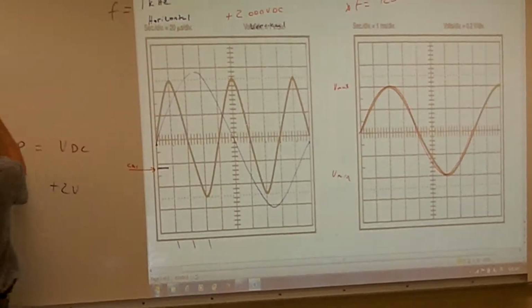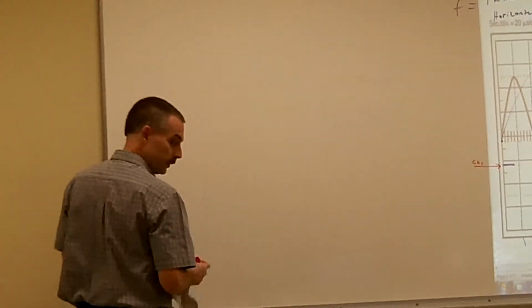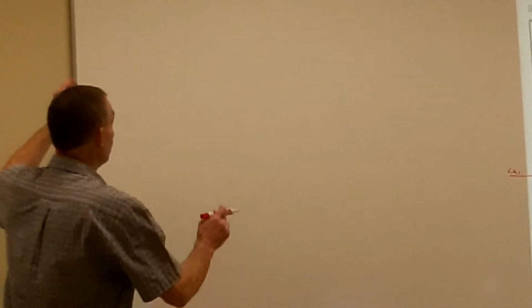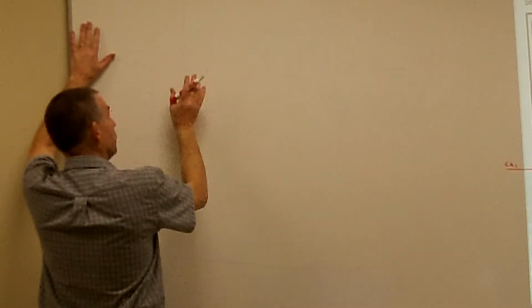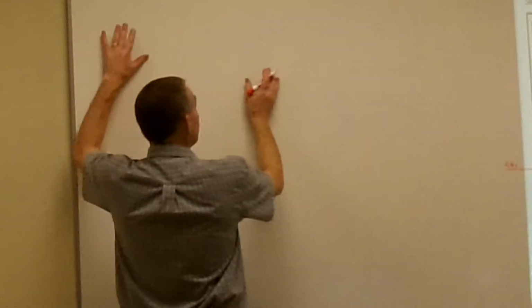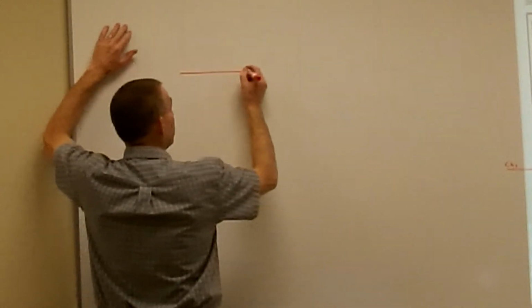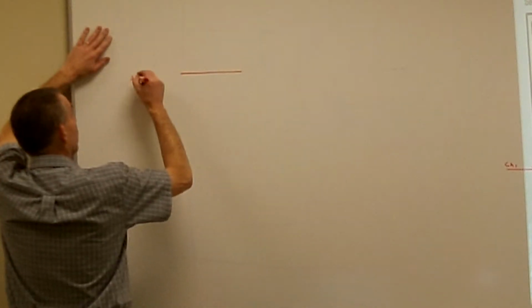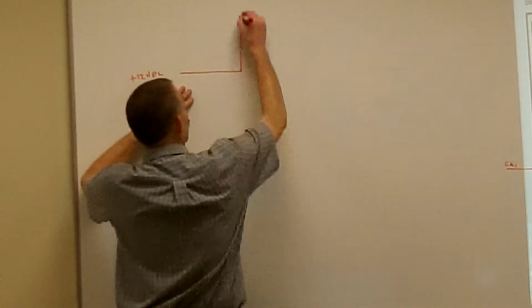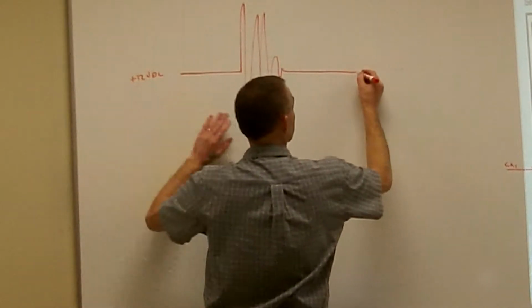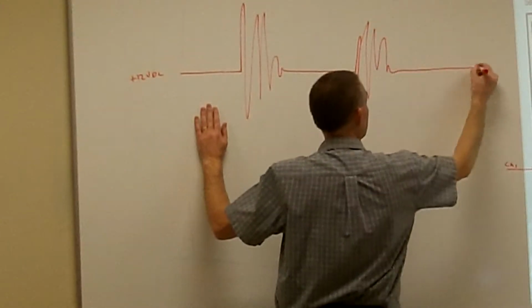But right now, at my other job, we're getting some severe common mode going through our rectifier. I'm trying to analyze where that common mode is coming from. Is it coming from our servo drives, or from our PC, or where? When I display it on my oscilloscope, my signals look like this. I know I'm sitting on a plus 12 volts DC reference. It goes along just fine, then sits at my 12 volts, nice and clean, which is what I want. Then all of a sudden the thing just starts, and it's very repetitive.